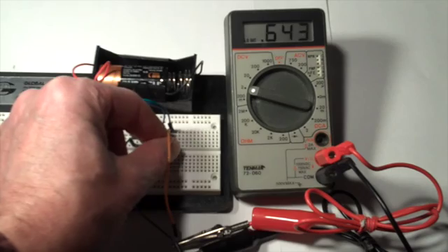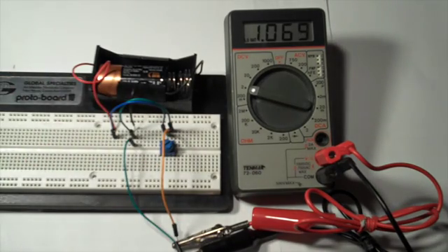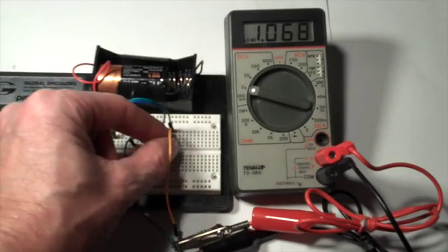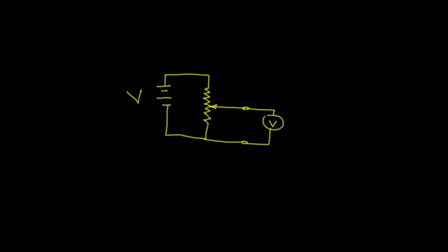Here I'm using a very tiny adjustable resistor to select voltages from a flashlight battery. Although this device is nice and compact, it goes from one extreme to the other in less than a whole turn. Here is how we would diagram this circuit. When a variable resistor is used in this way to provide a selectable voltage, it is called a potentiometer, since we are metering out a potential energy or voltage value.